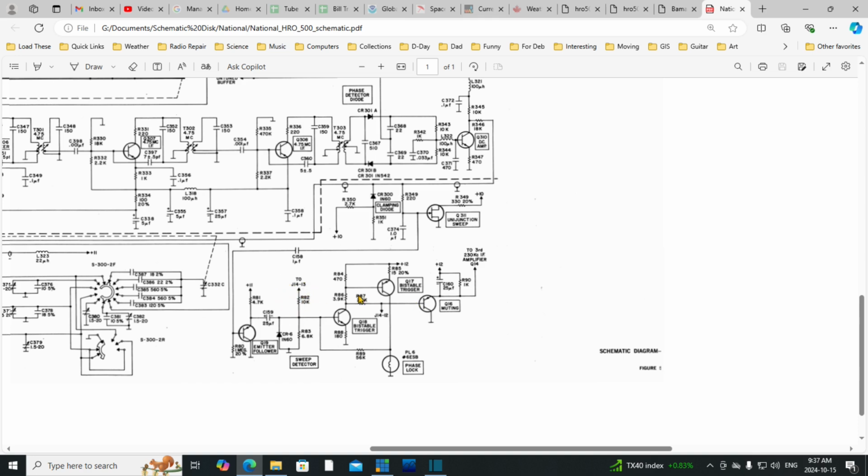It's this one you ground, and no, I think you can ground this one, or you put 12 volts on this one, one way or the other. You can play around with muting this radio externally. So maybe that would work with some other equipment, like a transmitter or something. You can mute the radio when you transmit.